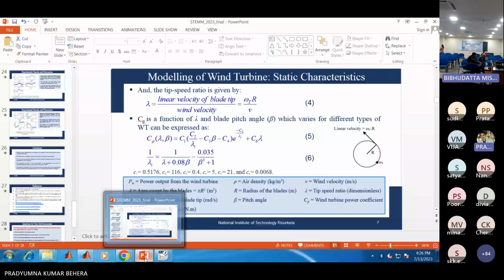Similarly, we have a voltage control mode also. Whatever I have told now is related to the average current mode control. There is another control, that is the voltage control mode, in which there will be no current control. We will compare the output voltage of the converter with the actual reference voltage, suppose we have set 48 volt or 100 volt, right?